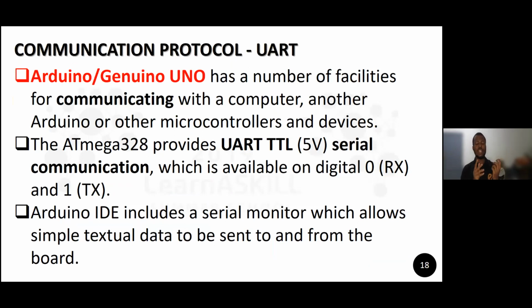Now, the reason I said don't use this TX and RX pin is that, from what I've experienced, anytime you connect them to something else in your circuit, when you try to upload code via the USB, it doesn't work.